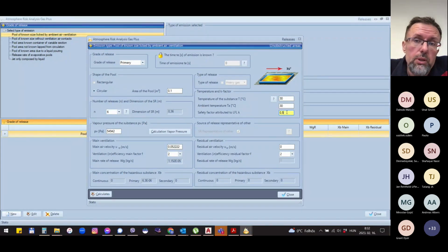And certainly the 2015 edition with the K factor 1 to 5 gave us a kind of limitation in the calculation. But now in the 2020, you need to give it by yourself. Many people forget it when doing the design, doing the hazardous area classification.